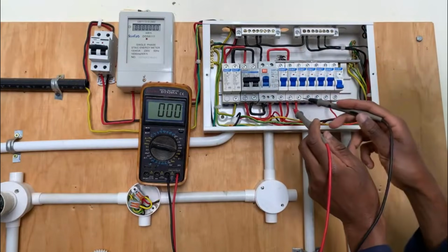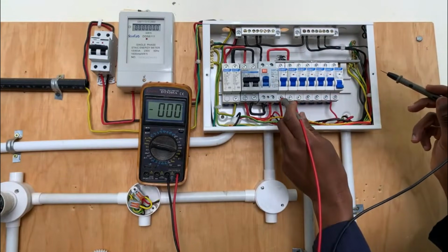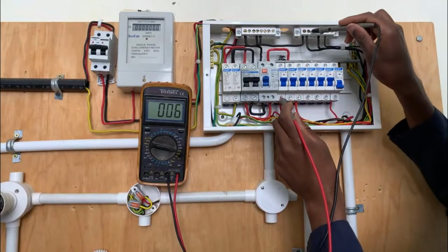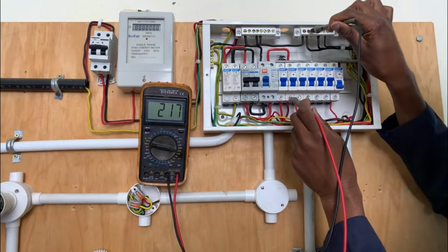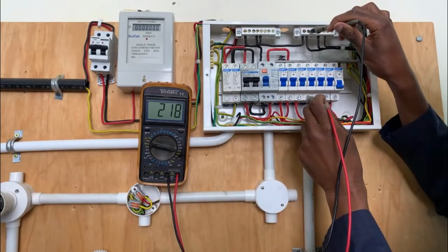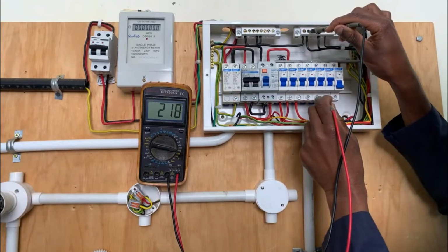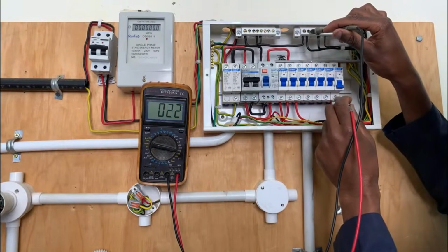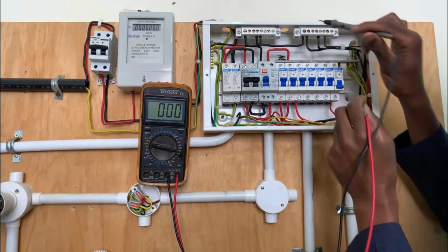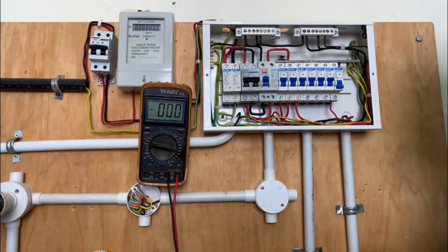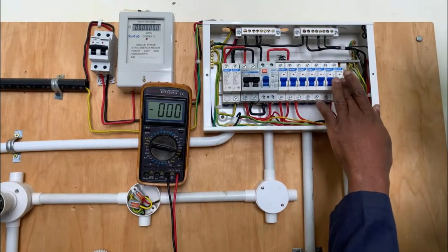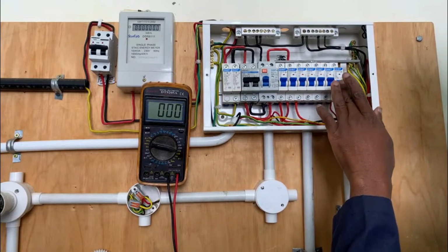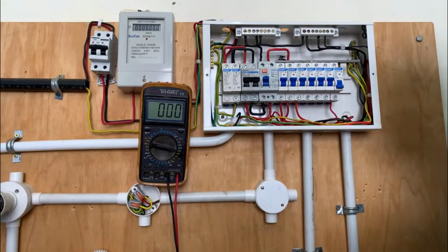At the output of all these circuits, we expect a reading. If you place right there at the output of every MCB, we expect that there is a reading, as you can see on my digital multimeter. All of those MCBs have an output, 218, 218. Lastly, we have 0 for the MCB that has tripped, meaning that voltage is not going through. Now, because there is a problem and we don't want to put it on, we don't know whether this MCB is faulty. What we will do is to isolate that circuit.